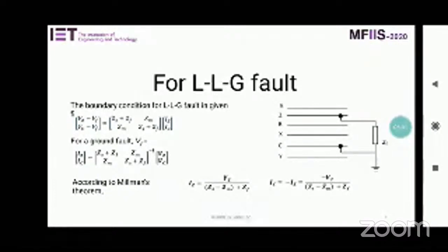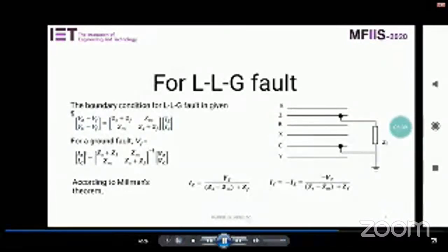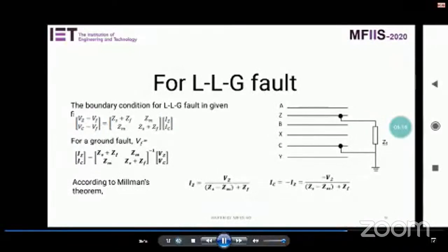Line impedance is taken as 0.1408 plus j0.644 ohms per kilometer, and the mutual impedance is taken as 0.1821 plus j0.2824 ohms per kilometer for both cases.